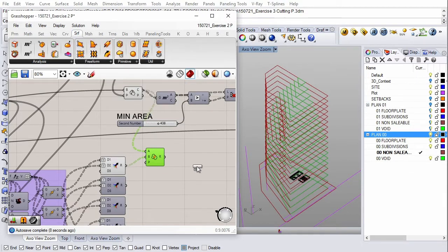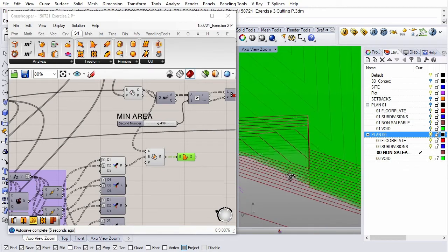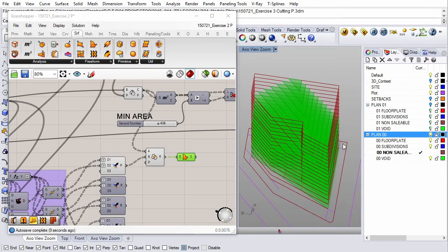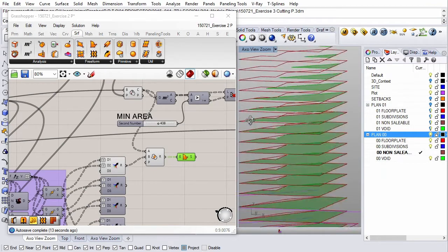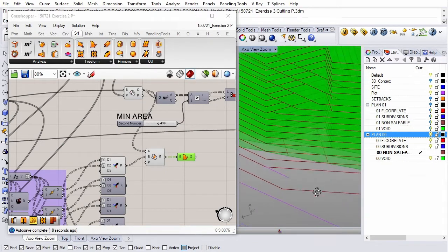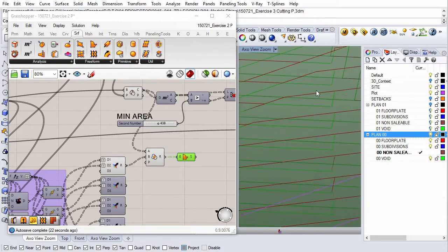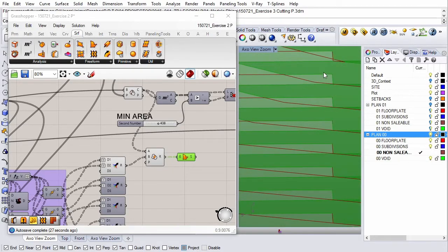We turn this into a surface, and we can see what we're creating. In the areas where we sketched all the way up to the setback, that conforms to the volume. The areas where our sketch floor plate went inside a bit, that then comes inside from the setbacks.